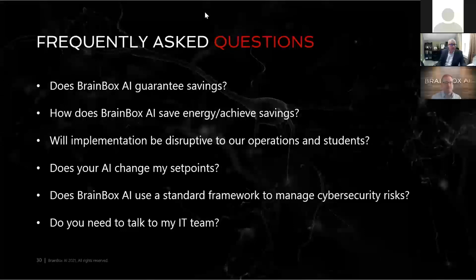Okay, well, we have a question that came in. Will BrainBox work in a building with pneumatic control or partial DDC with partial pneumatic? Yeah, so the short answer is maybe, and I'll walk us through the scenarios here. So in a pneumatic system, let's say it's a VAV type system, air handler, you have DDC controls on your chiller plant. You have DDC controls maybe on your air handlers. Maybe there's a few valves that still have pneumatics, but you still have a controller. But then all VAV box pneumatic systems.